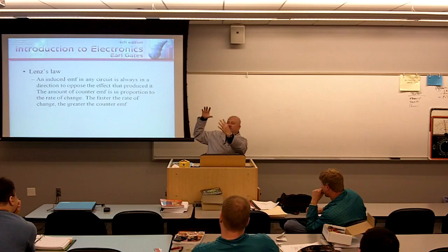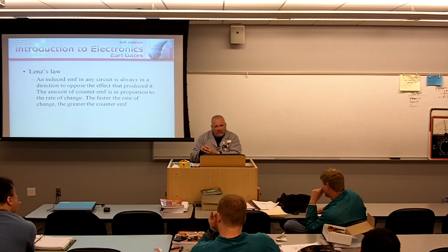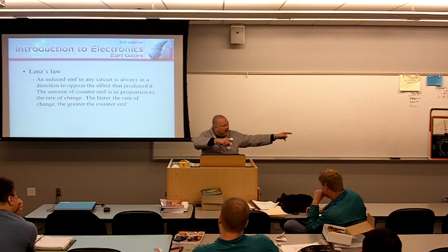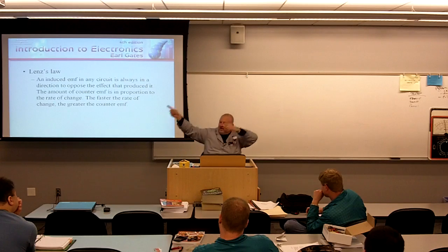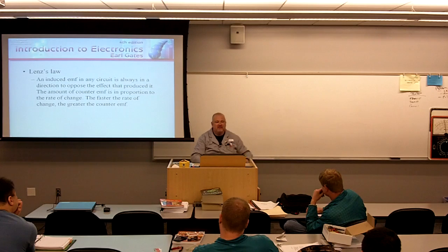If we shut the circuit off, that electromagnetic field is going to collapse, and it's going to produce a counter electromotive force that goes the opposite way of what created it. So if the EMF goes that way and creates some magnetic field like this, the magnetic field collapses, and it creates a counter EMF that goes in the opposite direction.